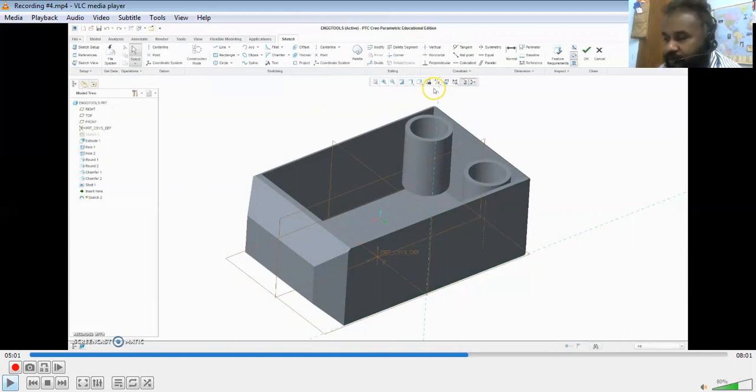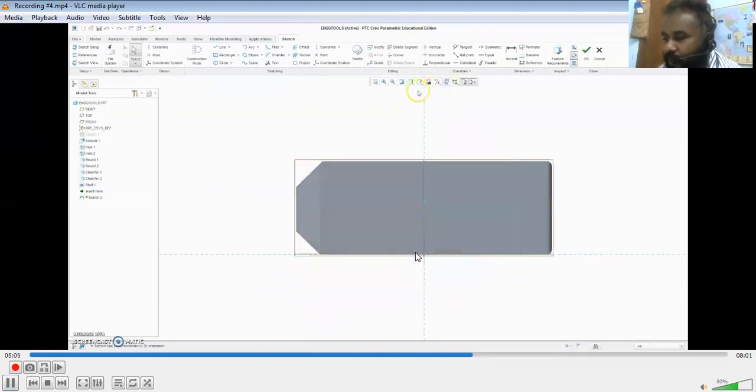As usual, I click the sketch part, and I'm going to get the plane view where I'm going to draw. Once that is done, I've chosen a rectangle. I'm choosing a corner rectangle so that I can choose from this corner to any particular corner where I wish to draw.